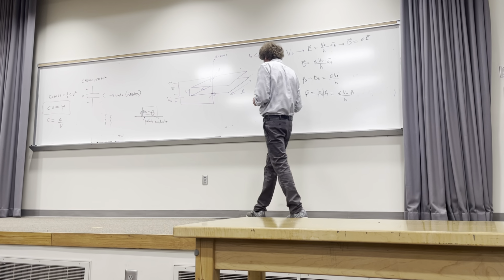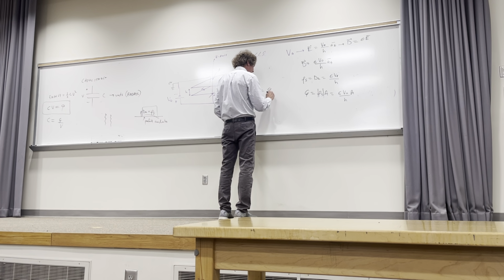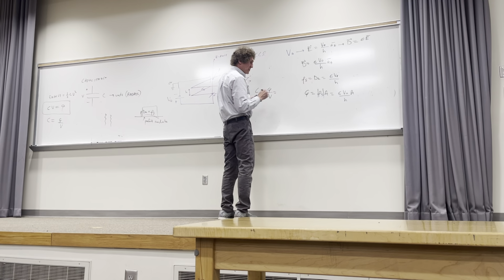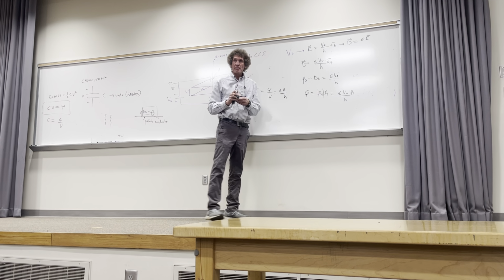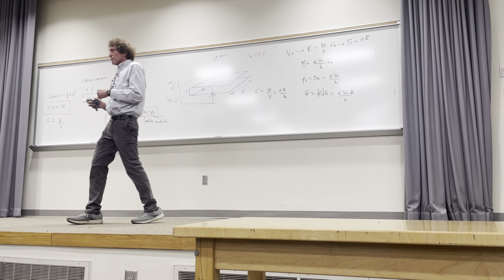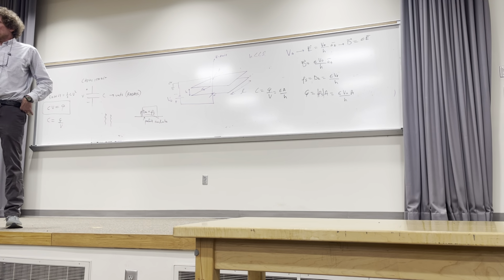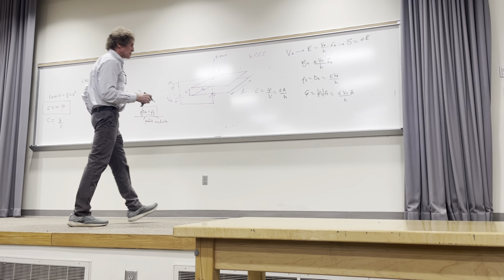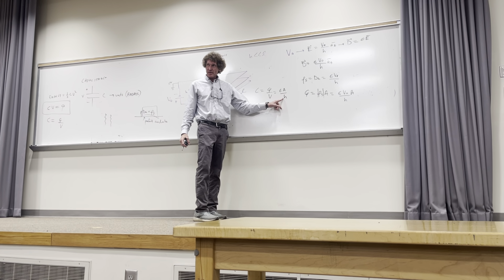And then finally, to get capacitance, I take Q over V, and here, Q's right there over V. It just means capacitance is epsilon A over H. Do y'all follow me on that? Now, this is for a parallel plate capacitor. This is one you probably should know because of your physics courses. But remember this, capacitance is always going to be proportional to the plate area and always inversely proportional to the distance between the plates. You all see that right there? For a parallel plate capacitor.